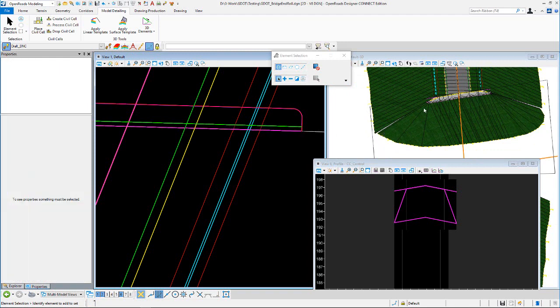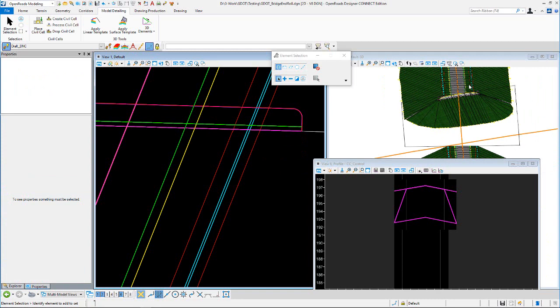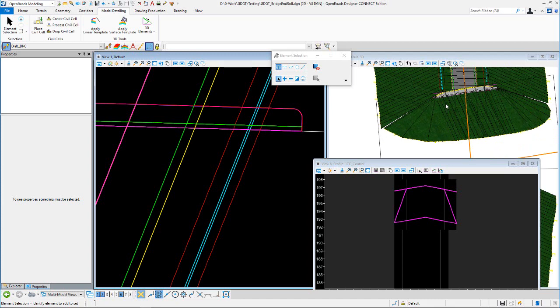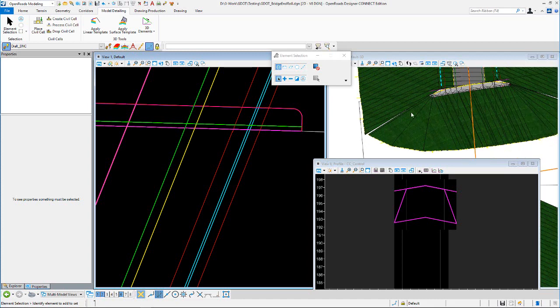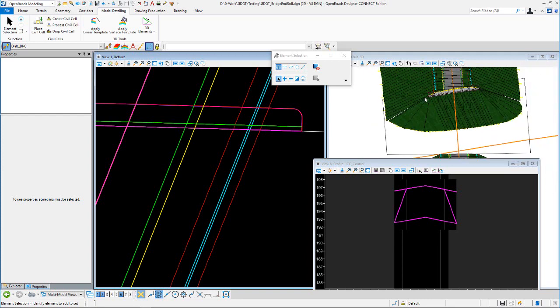So, if it's a 2-to-1 slope at this point on your mainline corridor there, and this is actually a 2-to-1 slope in this template, the reason they're not lining up, there's still a little gap there, is because we're cutting across this roadway skewed. If we were at 90, we'd be lined up perfect, right? As long as we got that point right, that bottom would be lined up right. But since we're going across it skewed, there's a little difference on that.